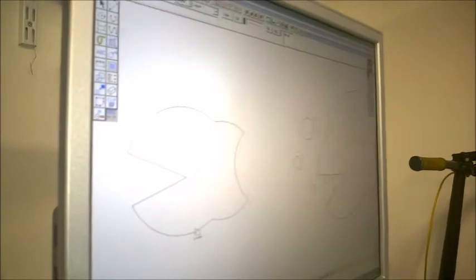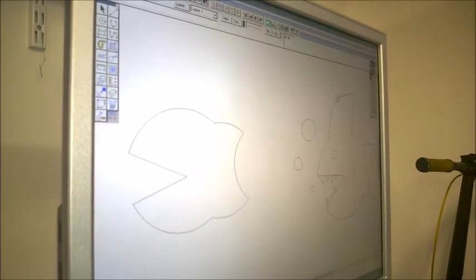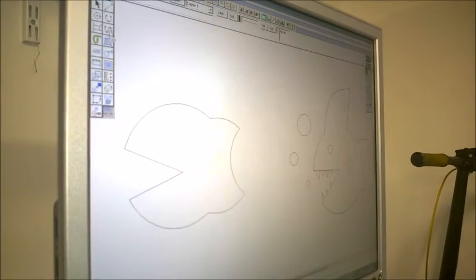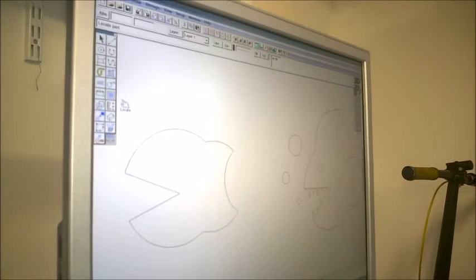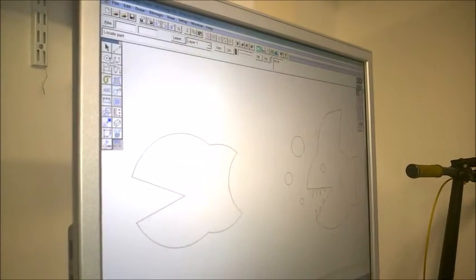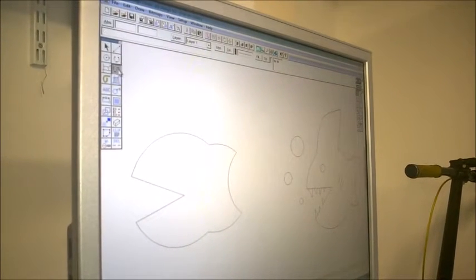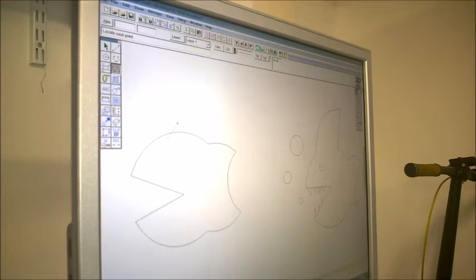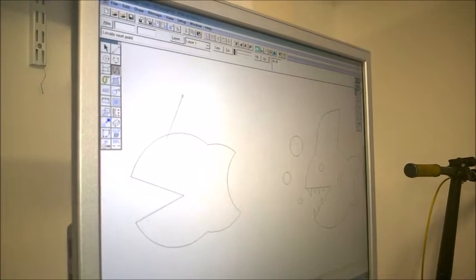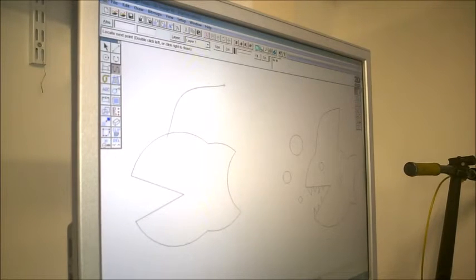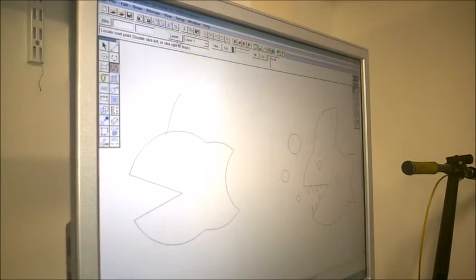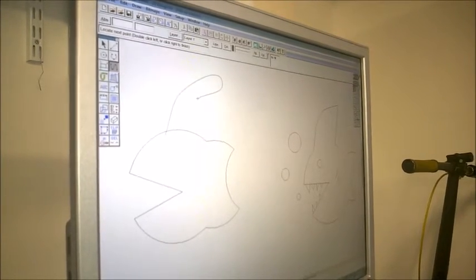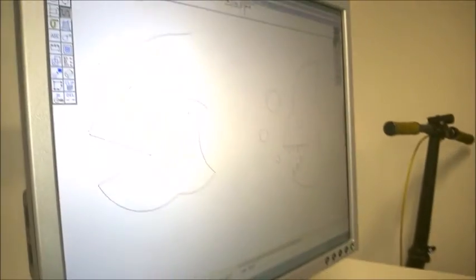Okay, now the next thing I'm going to do is his fin, or something like a fin. I want a slight curve on the fin here, so I could use a couple of tools. I could use an arc or a circle, but I'm going to use the path tool here, and I'm literally just starting again, overlapping the shape and starting where the curve is going to go from and to. Now sometimes when you use this tool, you click again and you don't know how to get off of it. It's a simple task.